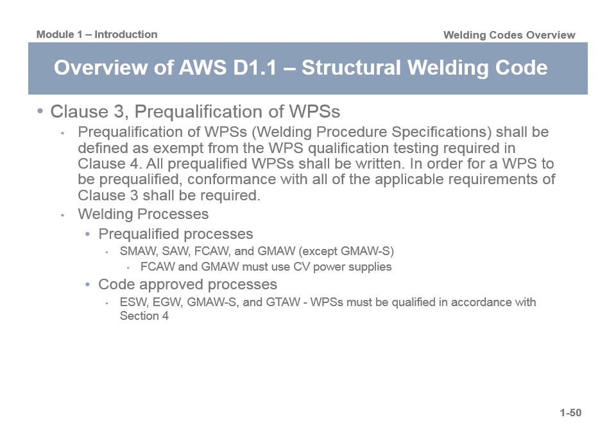Basically anything below about 21 volts is considered short circuiting. Anything above that, 21 to 25 plus or minus, is globular, and then anything above 25 is spray. But you can't use GMAW, gas metal arc welding, short circuiting, and have it be a pre-qualified procedure. You can qualify it and use gas metal arc welding short circuit, but it can't be pre-qualified.